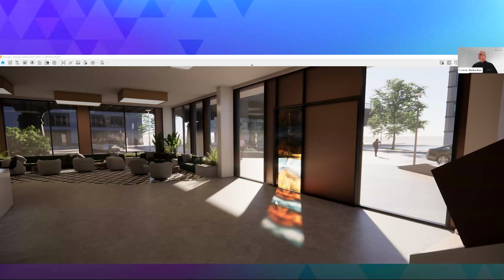No, our 3D artist team made those. Gotcha, just curious. Obviously, we have the custom asset editor too, so you can create your own custom Enscape assets as well. You can go to third-party sites like Evermotion or TurboSquid, get models from there, bring them inside of the Enscape asset editor, create the asset and apply those. I guess technically speaking, you can export a building from Revit as an FBX and load it up in the Enscape asset editor and make it an asset, right? Yep, exactly, because our custom asset editor will take FBX, OBJ, and GLTF files.